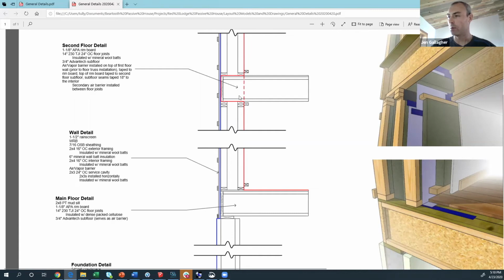All right, so then if you move up, like I showed on the pictures, we had a double stud wall. We were just 2x4, 16 inches on center. We had 7/16" sheathing. We were all mineral wool insulation, so that 2x4 plus a 6-inch gap plus another 2x4 got us 13 inches.